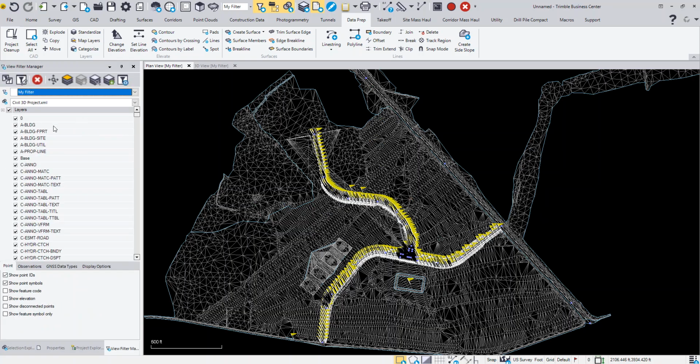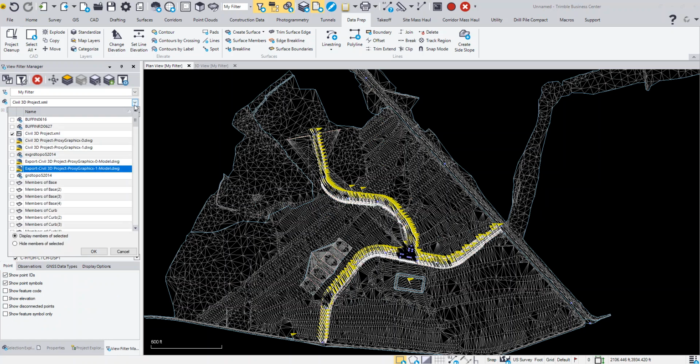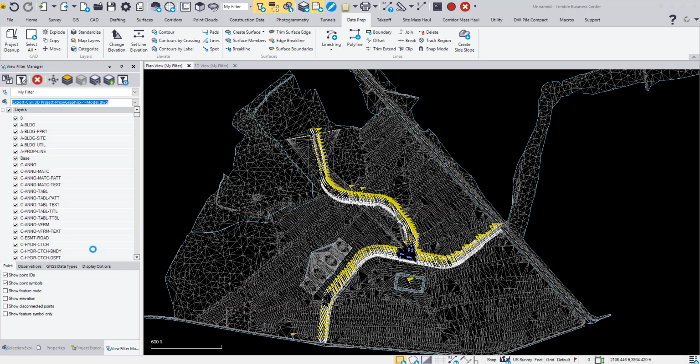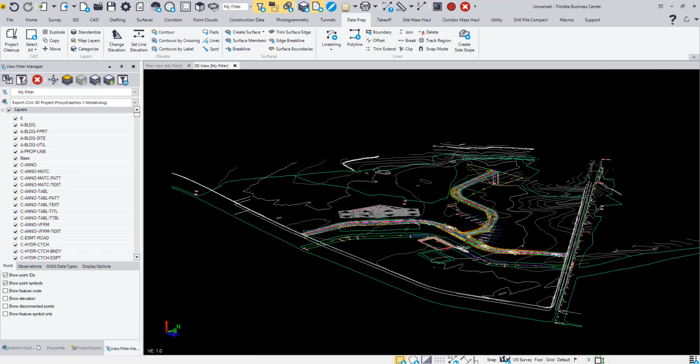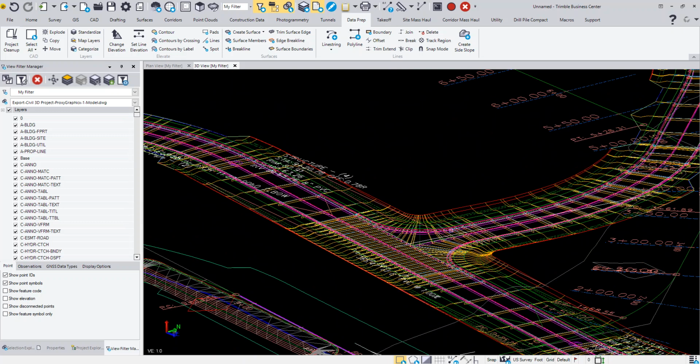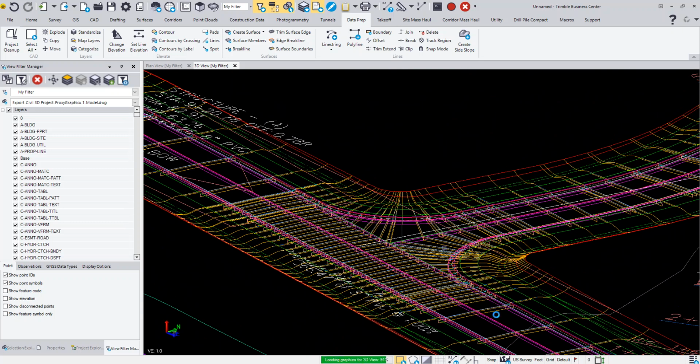So when I bring in that drawing, and this doesn't have anything to do with the LandXML in this case, it's just the proxy graphics set to 1, or the actual, let's go to the export one as well. So if I do proxy graphics or export, either one of those, as long as they're both set to 1, you're going to see what I'm going to get here. Is that when I look at this corridor now, especially in this case, the exporting, I get the 3D lines,